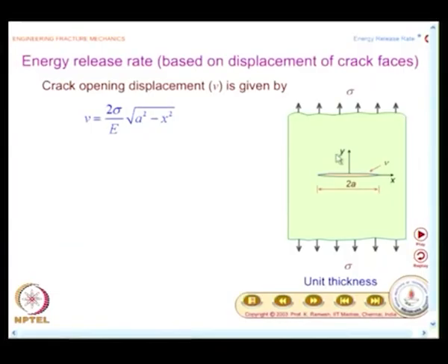Now, let me take up a problem of a center crack in an infinite plate. And mind you, we are using the equation for a biaxial stress field for a uniaxial loading situation, and we have seen some kind of a justification for that. And in the first methodology, we would confine our attention only to the infinite plate with a central crack. We will confine our attention only to a typical problem for which we know everything.